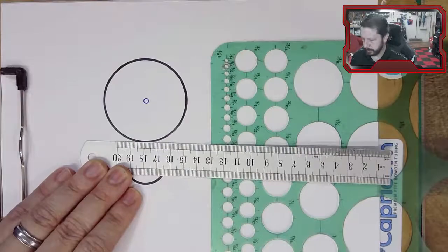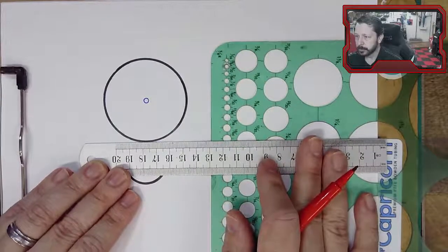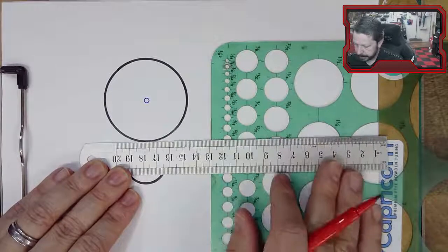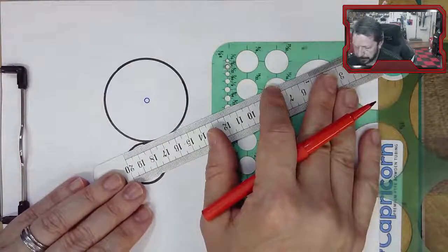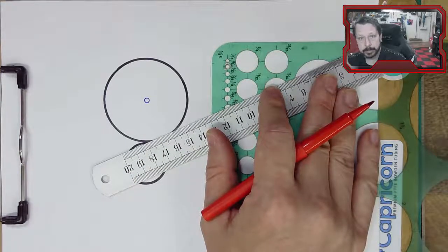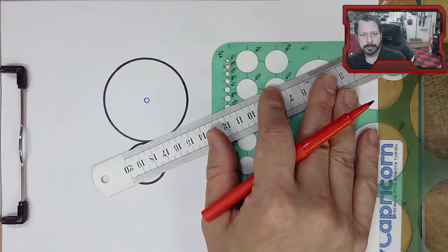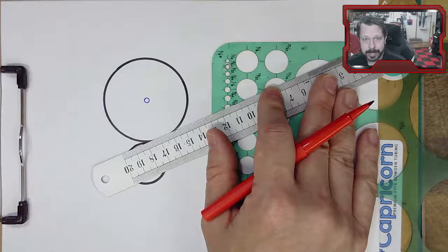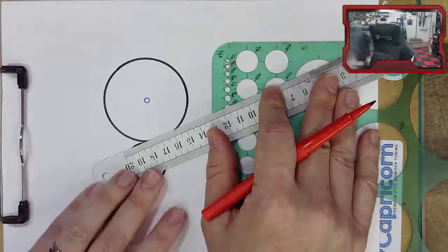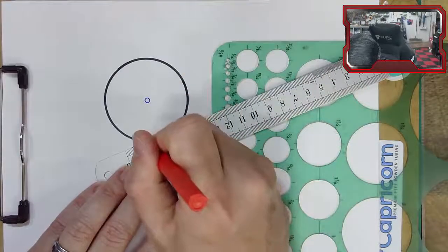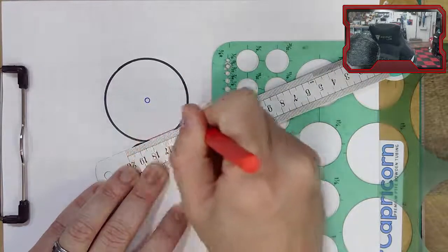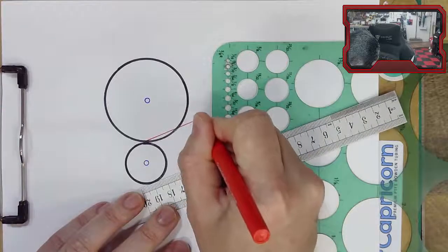Let's see if we can make these things on the screen more horizontal. And it's at a 20-degree angle. And there are 3 common pressure angles: 14.5, 20 degrees, and 25 degrees. It used to be, back when people were hand making gears, that they were almost all custom made and there wasn't a standard. But now we have these 3 common pressure angles.